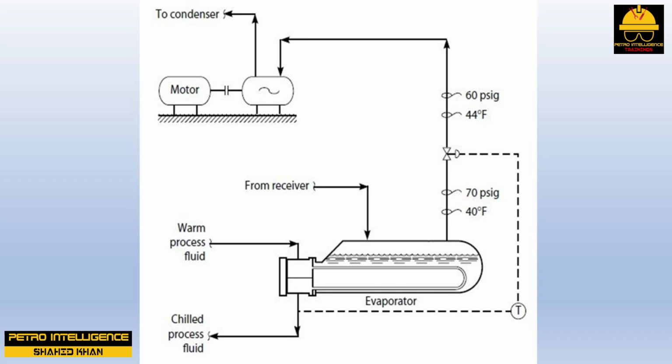As we lower the compressor discharge pressure, the compressor suction pressure will also decrease. This will have the normally beneficial effect of reducing the evaporator pressure and temperature. Now that the evaporator is cooler, we could increase the flow of warm process fluid to the evaporator. Thus, improving the efficiency of the condenser will increase the capacity of a refrigeration system to cool. This happens mainly by lowering the compressor discharge pressure rather than producing a colder condensed refrigerant.